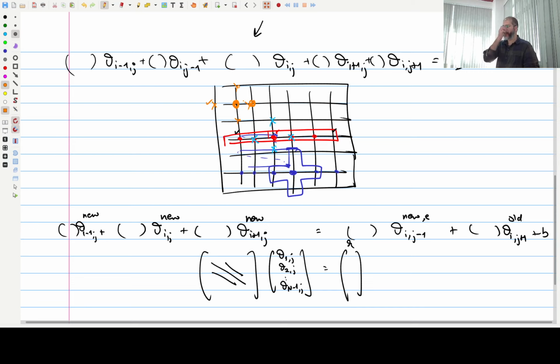But you might ask, that is fine, it will converge much faster, but does it necessarily mean that... see, we are reducing the number of iterations or the number of sweeps. But to solve the TDMA, we require some computational effort. It could happen that the computational effort required for solving the TDMA may be more, because ultimately we're talking about the number of floating point operations that the computer has to perform.